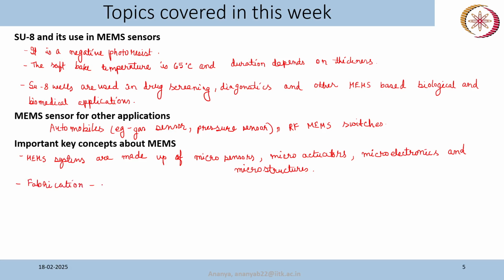Fabrication involves deposition, then patterning. Even if you want to make a very simple resistive sensor, you should go for patterning, because you will need some electrodes for your sensing material. Okay. So patterning or lithography is like the heart of microfabrication, that will be needed multiple times,